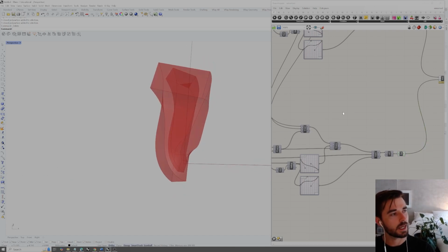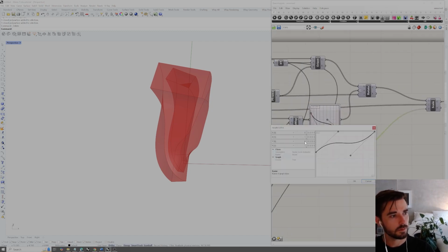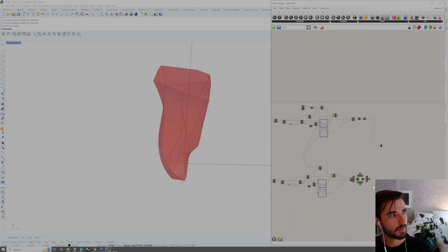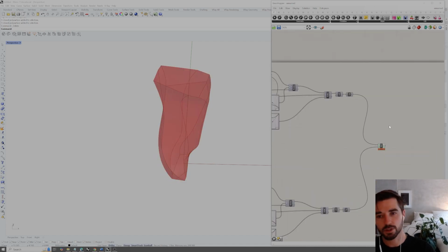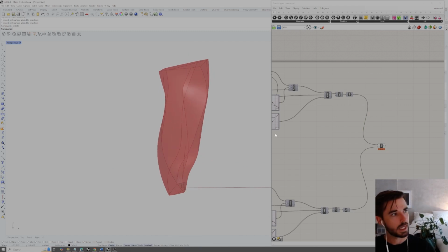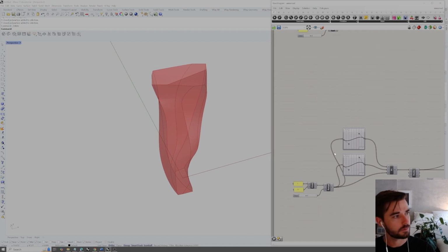And if we did the same thing with this geometry up at the top, change this to 0.5, and then an upper bounds of 2 for this scaling graph mapper, we now see a much larger, thicker geometry that is resulting. And that's just because we have more overlap and more mass to start with.